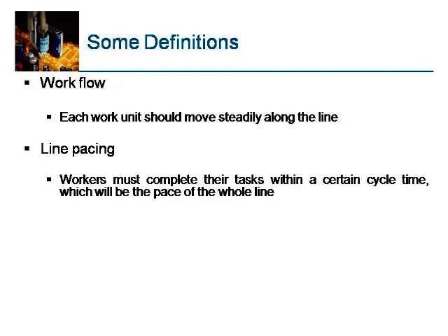When the workers are standing across the line, and the line is moving slowly, the workers are supposed to complete the assembly as per the assembly time only. The pace of the movement of the work part is fixed. Accordingly the speed is set, and by the time a work part comes to the vicinity of the worker and leaves it, he has to complete the task given to him. Otherwise, you will get incomplete assemblies.